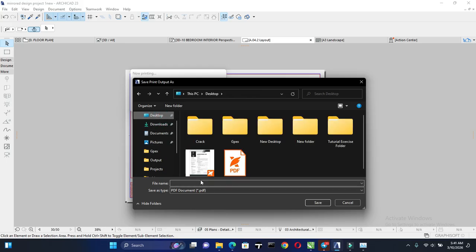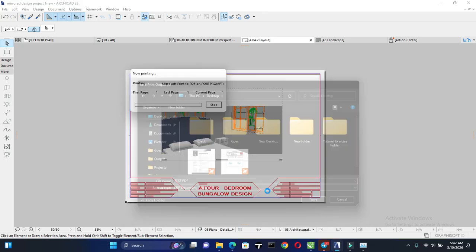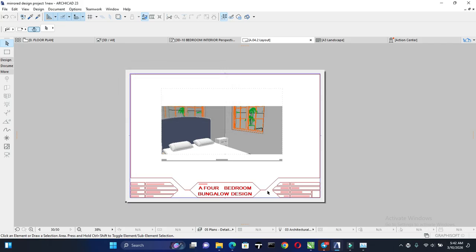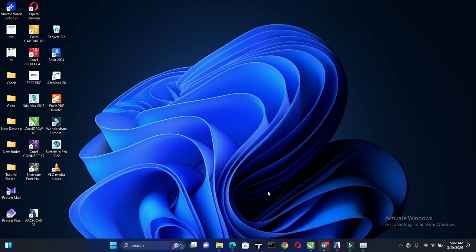What else do we need? Okay, so this is where we are now. That's that for converting documents into PDF and all. What else? Pen sets and graphics override. Remember how we changed our pen from here, options, elements, there's pen and colors. That's where we change our pens.